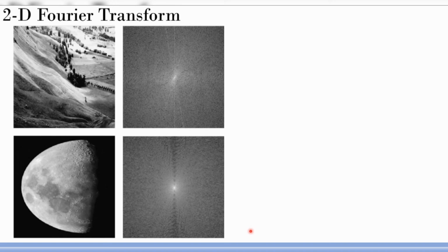So I would like to stop this particular lecture by showing you a very important example. You have the Bay image and its Fourier transformation, which is represented here. One thing I did over here is that the center of the Fourier transform is the 0,0, u equal to 0, v equal to 0, lies at the center. The Fourier transform of this image is shown over here. Basically this is the magnitude of the Fourier transform.